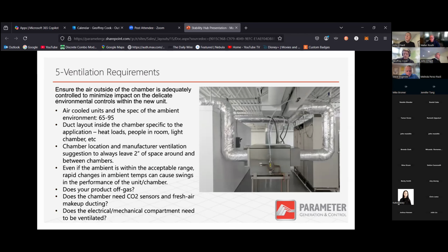Might add that when you do drain it, know where your drainage is going and what the local requirements are. Your company may be charged with knowing exactly what's in the water or certifying that there is nothing in the water as it enters the local municipal system. So just check on that location by location. Very good point, John.